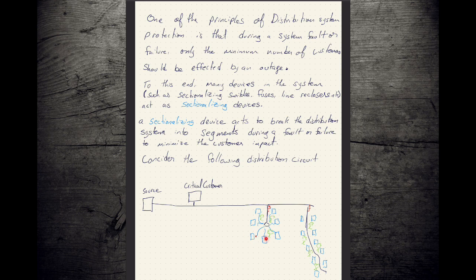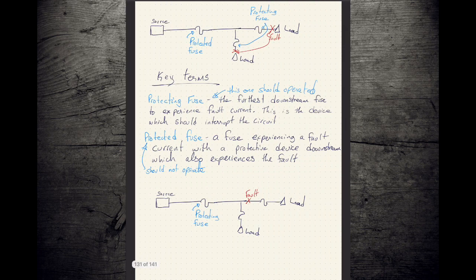There's just not much electrical load happening here. But then a tree branch comes down in the wind and boom, fault. So this fuse, before the fault happened, didn't have much load on it. But at the same time, the upstream device back here at the source, this could have been a factory and they might be running full production. So even though this might not be seeing much electrical load right now, the upstream device might be seeing a lot of electrical load.